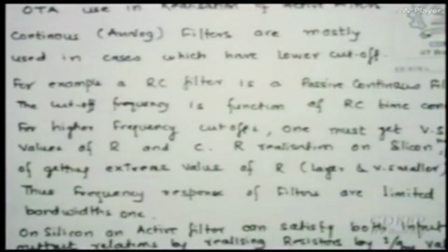On chip there may be parameters varying drastically, it may be 50% variations. And therefore very low resistances or very high resistances are not greatly realizable on silicon. In a circuit we can always say 1 ohm and fair enough, but when I do it in silicon I find that on 100 chips only 1 worked. That is something I am worried about. So active filters try to alleviate some of those problems, and therefore OTA based filters have become very popular.